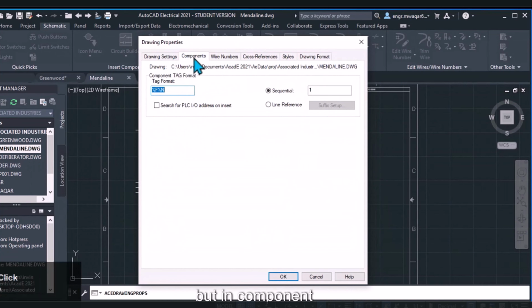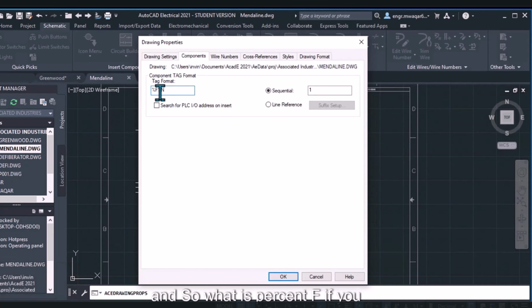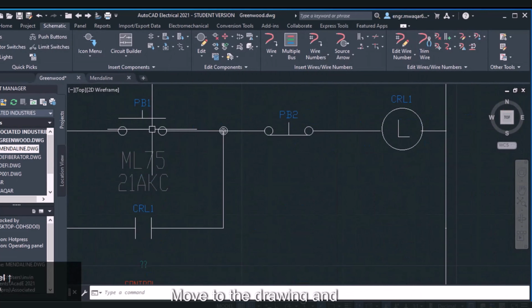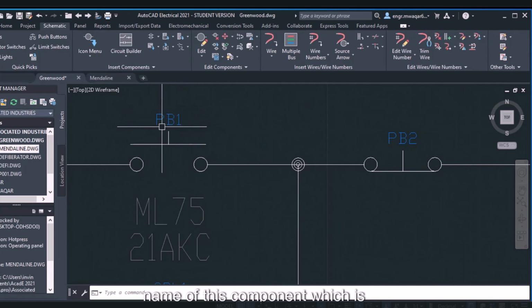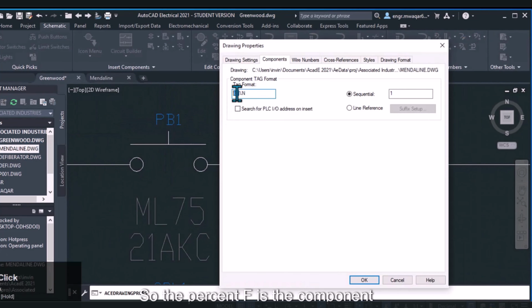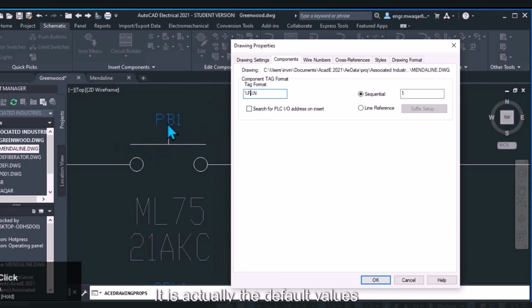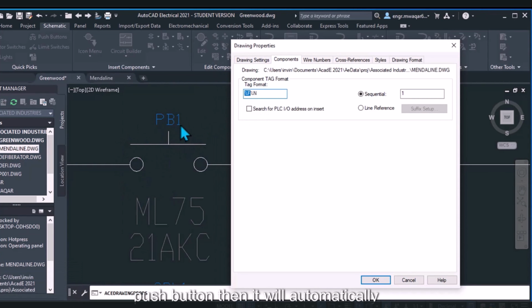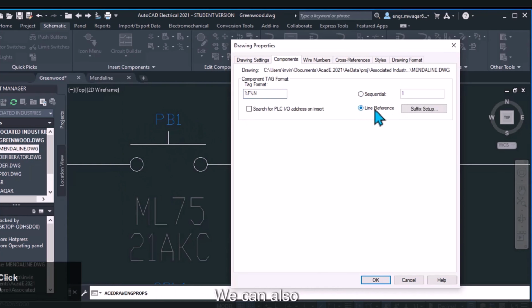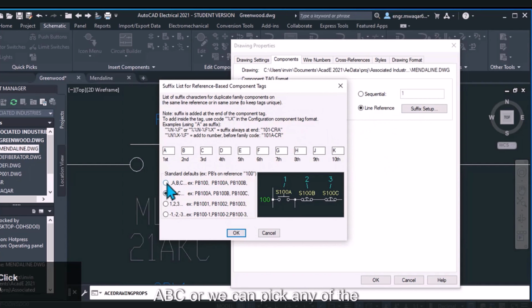The software treats these as entirely separate dialects. A push button in the NFPA library visually represents itself completely differently than a push button in the IEC library. The actual geometry of the shape changes. Which is why the software actually forces you to set your standard at the project level before you even begin drawing. It won't even let you mix them up. No, it won't.